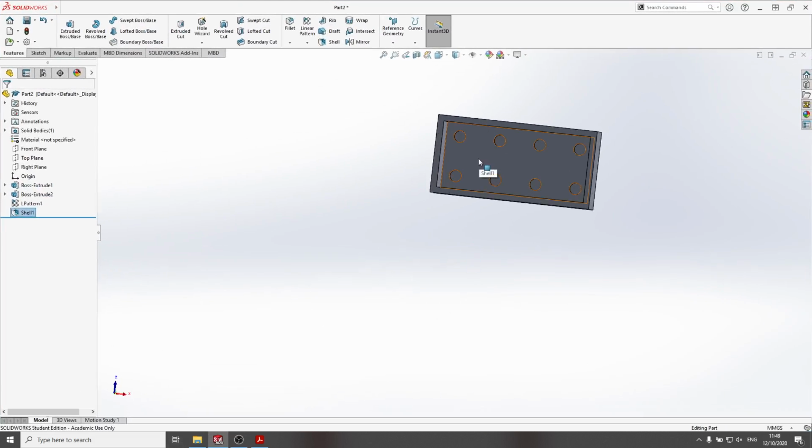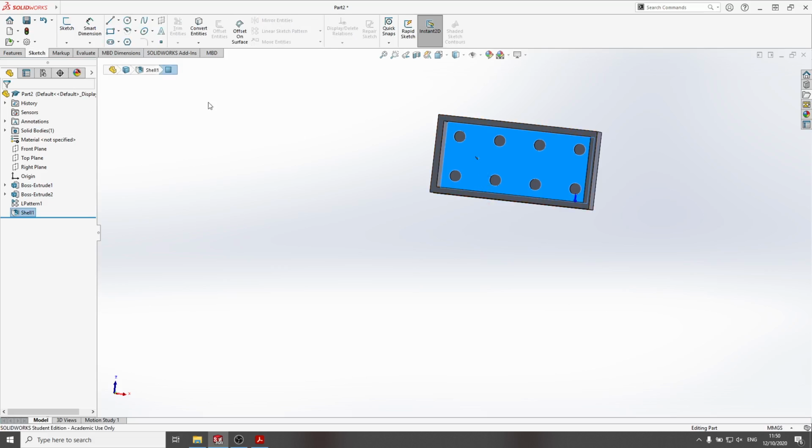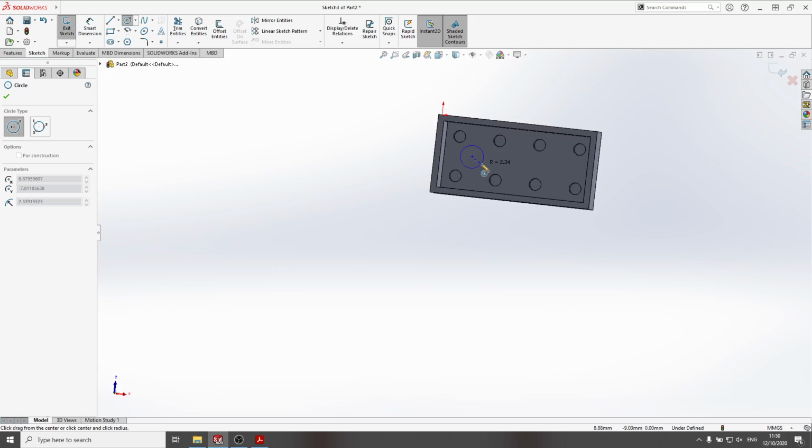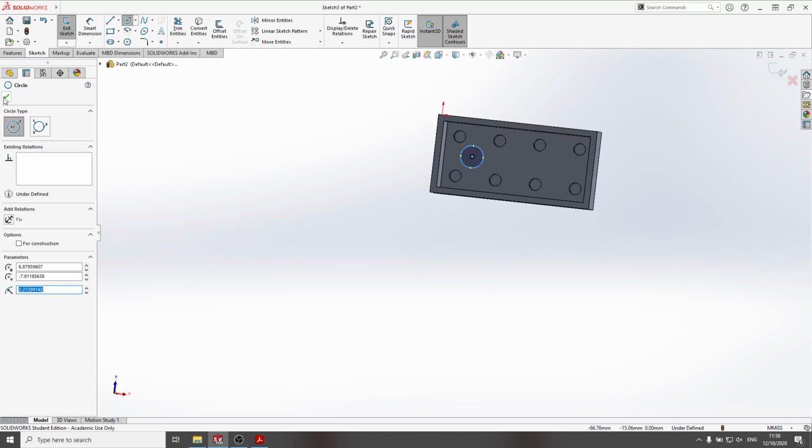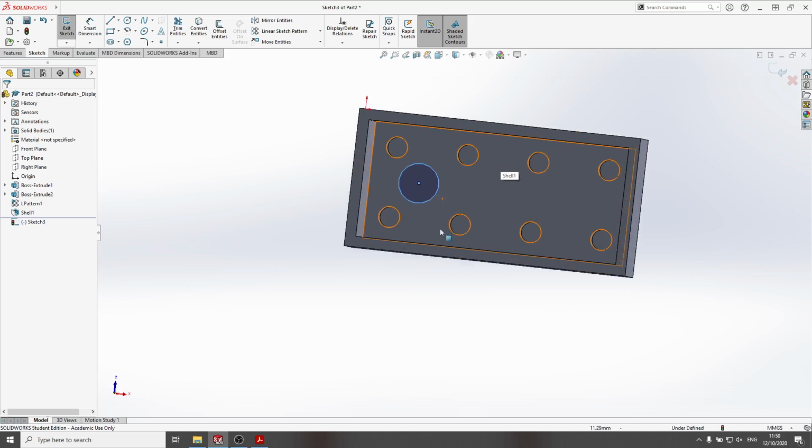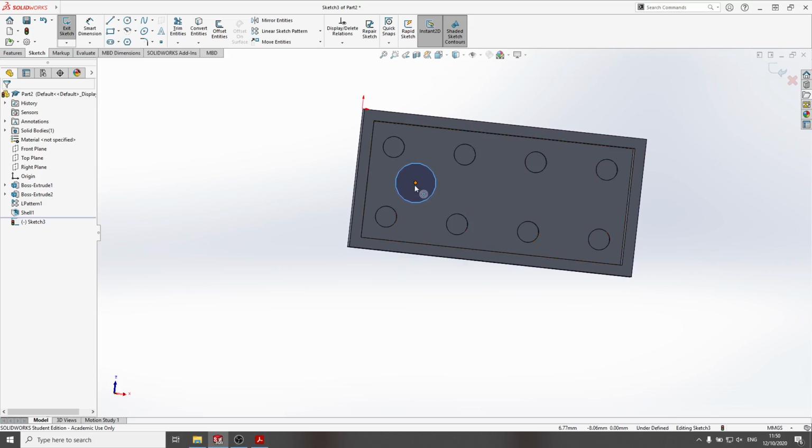So now we say inside here, we want to create those little tubes. So we create a sketch in here and just draw it anywhere. And then I'll take care about the dimensioning. So first of all, we are going to use Smart Dimension again for the diameter. And it has 4.8 millimeters inner diameter and 6.58 millimeters outer diameter.